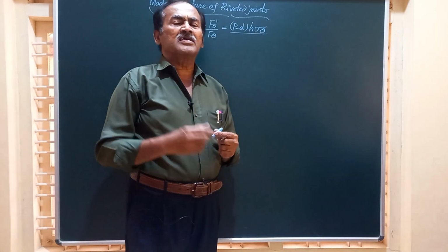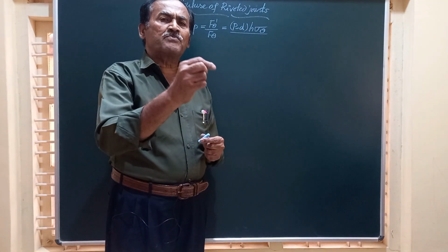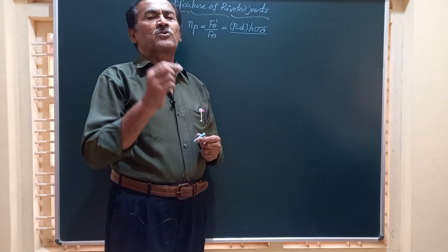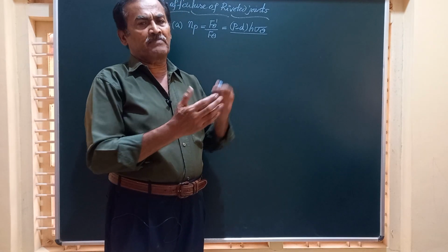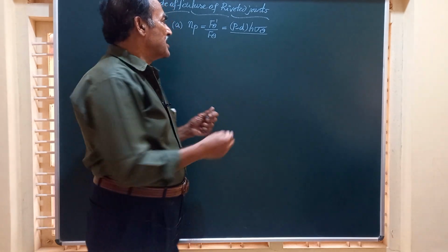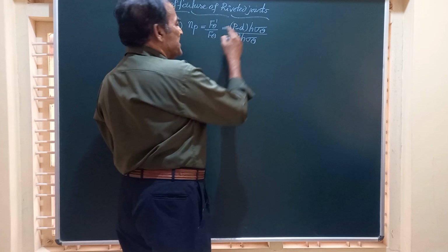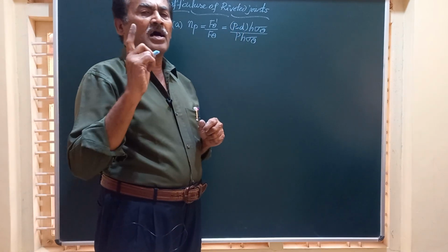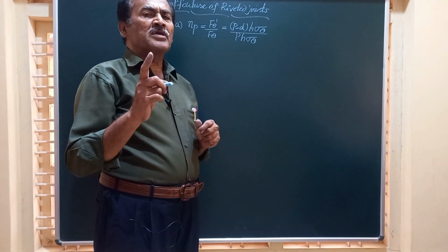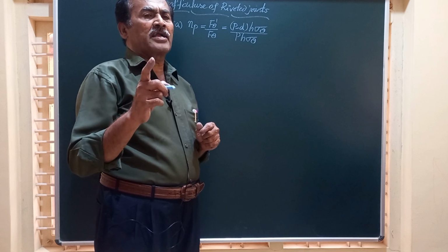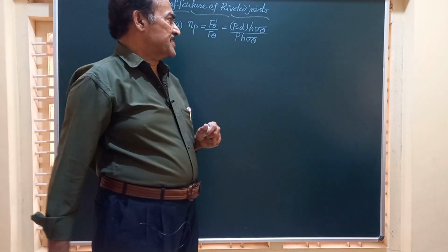F theta is the strength of the solid plate, a plate without any hole drilled in it, for a pitch length of P. So that is given by P into H into sigma theta. Friends, all these expressions are readily available in the machine design data handbook authored by any author.